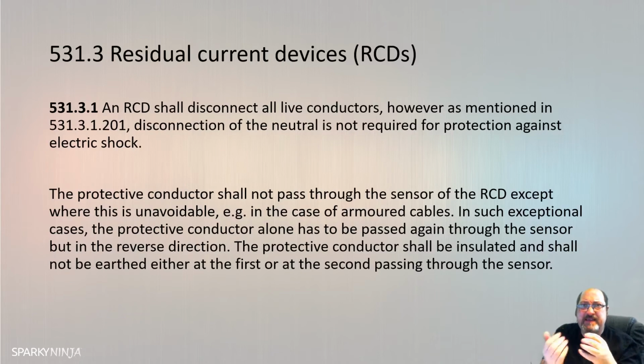So it's deducting itself. It's something I probably would be better to draw, but it's something that is just stupid. And I would really like you to tell me if you've seen this before and taken a picture of it, because it's quite an interesting circumstance here. But if you understand the principle of RCDs and the theory behind it, it should make sense. It's all about achieving imbalance of current and making sure the leakage current to earth does not affect the amount of current being sensed by the RCD.